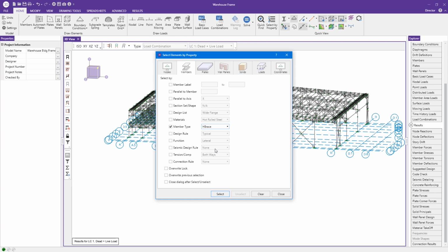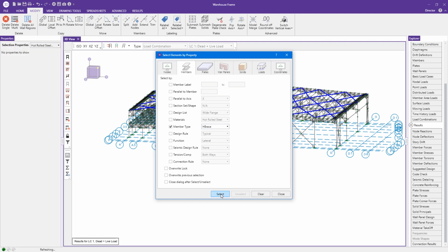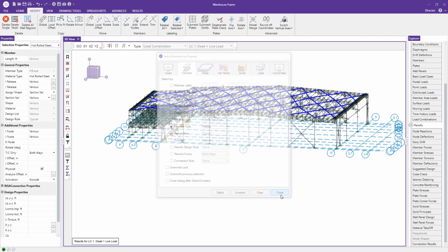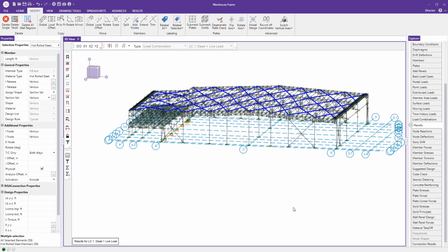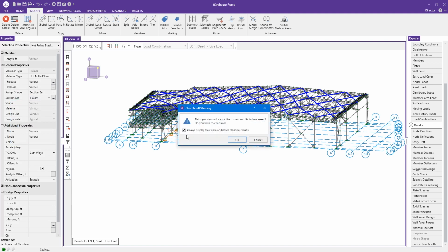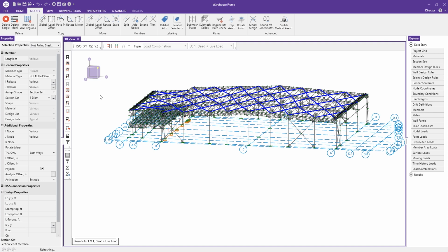And so I think the H braces are the ones we want to select. Once I select all of those H braces, I close that out. I now look at this model, and on the left side I can make a mass change to all of them. Looks like I have a variety of different members, but I'm going to change all of them to a certain section set. I have one defined called 1 inch diameter, and I'll make all of them the 1 inch diameter.